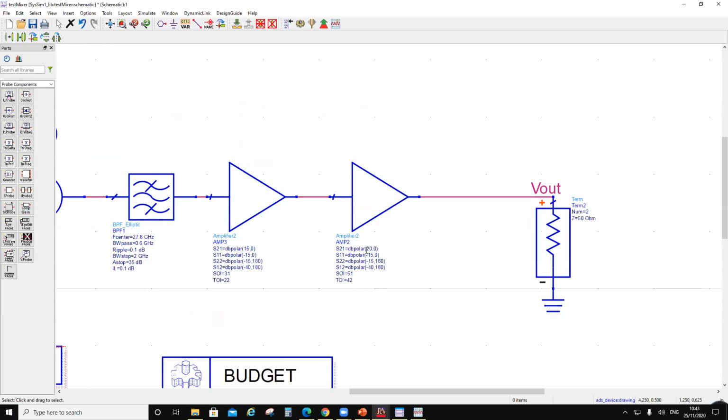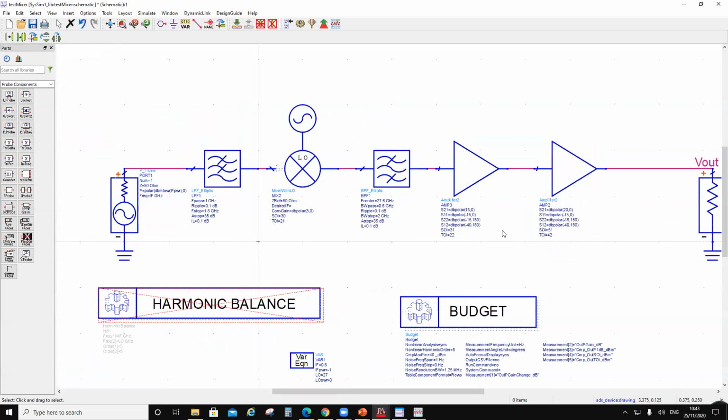So linear power, let's say the 1 dB compression is around 30. So I start doing my planning from the output side. Then this is 10. This has a gain of 22.5. So this should be minus 12, right? So minus 12. So basically that means that this should be around 0 or 2, right? So let's say I put here 2, and then this would be around 2 plus 9, that would be around 11, right? So you'll be over here.